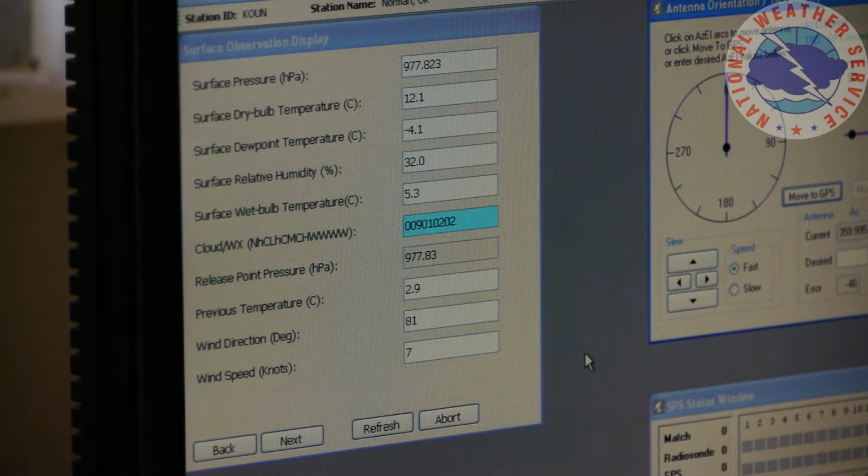It is also positioned directly over a GPS signal, and we're going to do a side-by-side comparison of the latitude and longitude. The critical part about this is we need 5 uninterrupted minutes of GPS data before this can be considered a successful baseline. And the pressure sensor must be within 5 hectopascals or 5 millibars of the precision digital instrument.